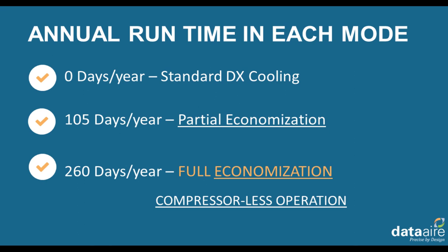So if you're seeing a trend there, a lot of these cities that get much hotter in terms of dry bulb also have very low design wet bulb temperatures. So if you're using some type of evaporative cooling tower, you can still take advantage of this and get very similar results to what we saw in Los Angeles.